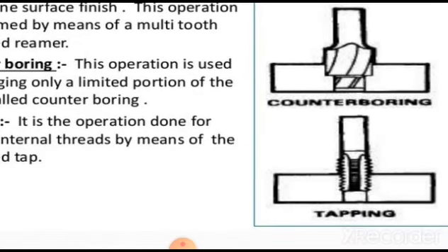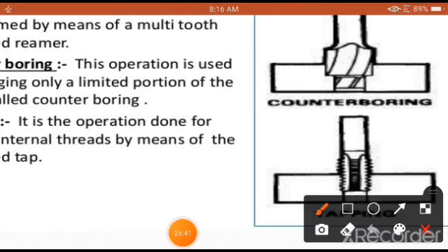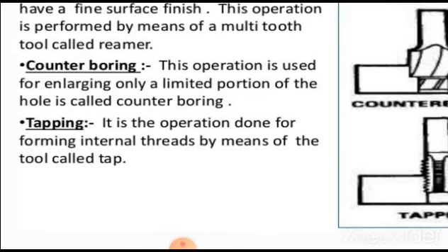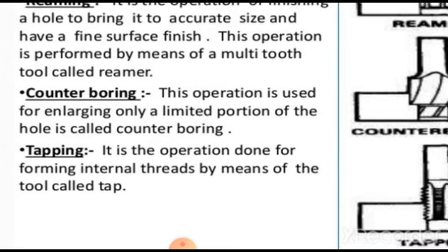We are not enlarging the complete portion. We don't want enlargement to the complete depth. We want it only to a certain depth in a workpiece. In such cases, we are going to use an operation known as counter boring. Next one is tapping.